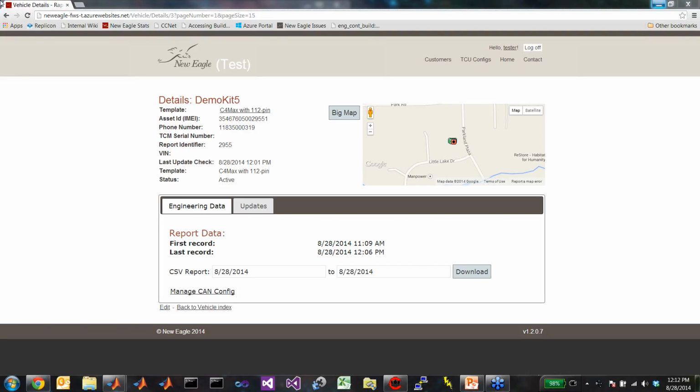The way we would do that would be you would broadcast a signal indicating what state it's in, and then we would log everything for all of the states. And when you're analyzing it, you could then see, based on what the current state is, which values are important. It's not necessarily the most efficient way in terms of data, which is a concern with all of this, of course. All the data is being broadcast over the cell network. So the more data you broadcast, the more frequently, the higher your data charges are going to be. But that is how we would address that right now.